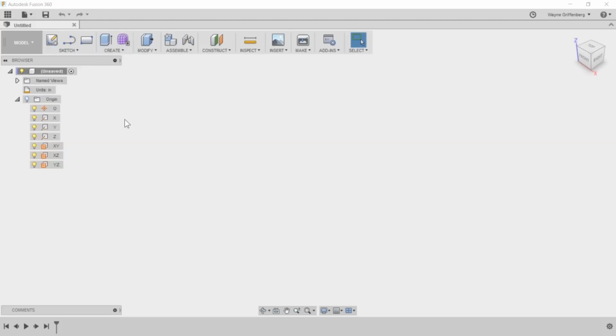And so therefore, it's going to be going around my x-axis. So I want to be able to design it in such a way. Now, you don't always have this opportunity. A lot of times when you're working in your shop, you don't really have access to the part to be able to change it or design it the way you need to. But it's always good to know that you can orient it into position for machining. In this case, I'm going to rotate my part. Since I do have full design, I have my napkin sketch sitting here. So I'm going to rotate a tube around the x-axis.